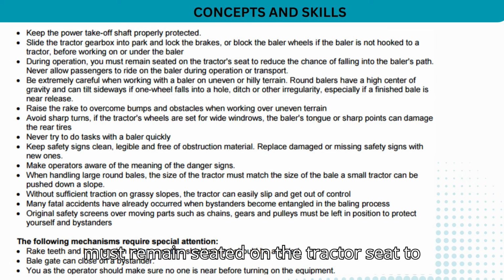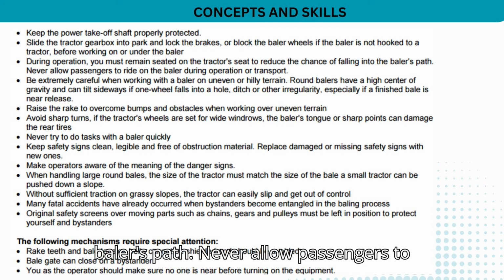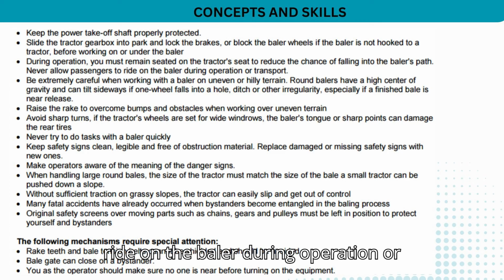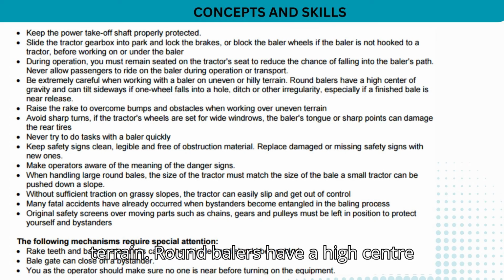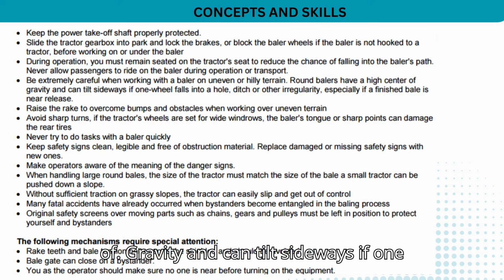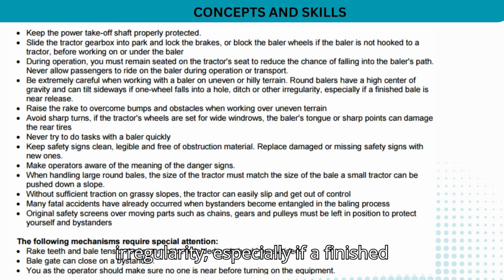During operation, you must remain seated on the tractor's seat to reduce the chance of falling into the baler's path. Never allow passengers to ride on the baler during operation or transport. Be extremely careful when working with the baler on uneven or hilly terrain. Round balers have a high center of gravity and can tilt sideways if one wheel falls into a hole, ditch or other irregularity, especially if a finished bale is near release.